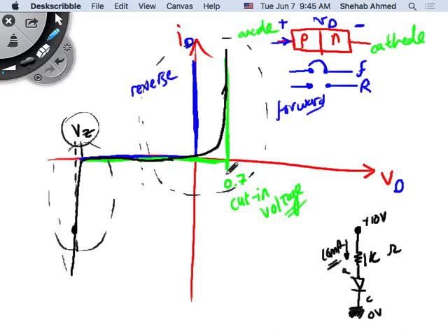Okay, this barrier voltage we were not able to control. This was around 0.5 to 0.7, 0.8. This was a fixed value, right? So in the forward direction, I have this fixed value of forward voltage. In the reverse direction, because it's not diffusion based, it's drift based. It's a different phenomena that's causing the current to increase.